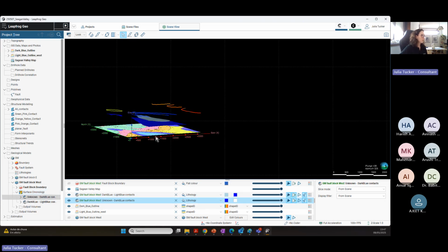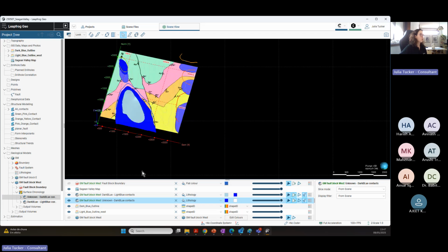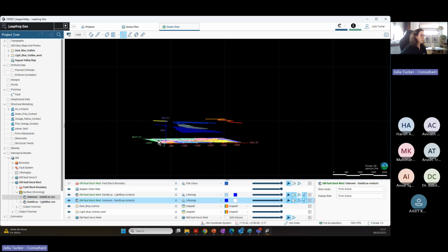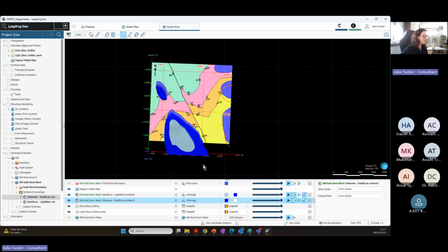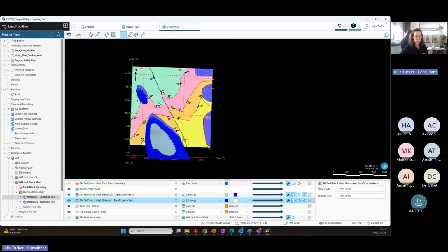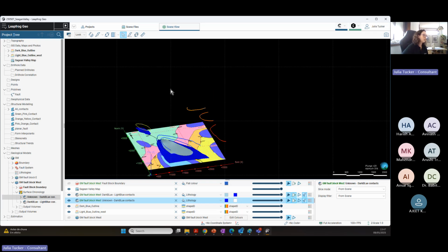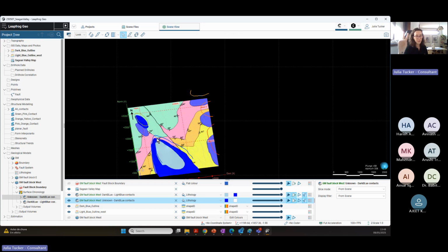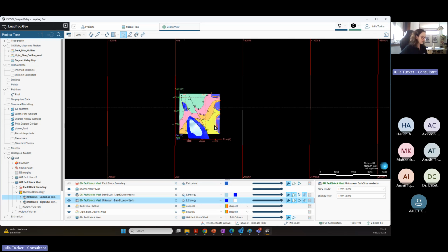And by dragging and dropping, we can see that this, for now, is working for us and is not interfering with the rest of the deposit. So why am I using these specific rules right now? I am still using youngest to oldest, but not exactly focusing and already doing the contact right here, because I have two different sources. I have GIS data, and I also have a CSV file as sources.